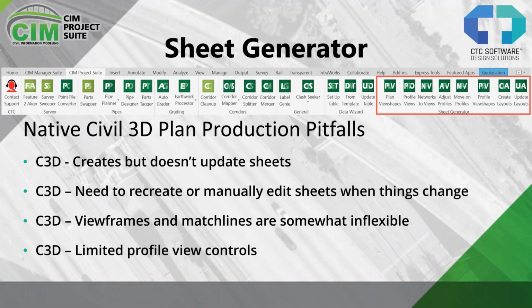But what are some of the native Civil 3D plan production pitfalls? Civil 3D view frames will create, but they won't update. So you'll need to recreate or manually edit your sheets when things change. The view frames and the match lines are somewhat inflexible in that way, and there are really limited profile view controls.